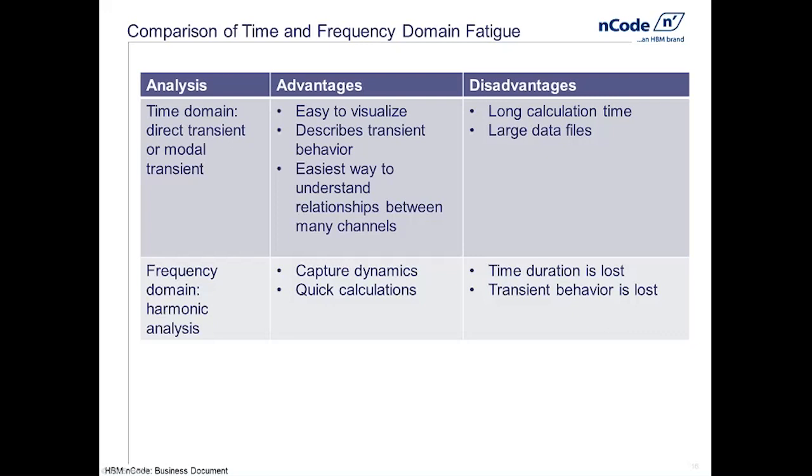The calculations are quick, but we have to keep in mind that we lose time duration, and also we lose transient behavior. As we have seen before, some time series data has transients in it. Those transients drive large stress cycles. We need to keep track of those.